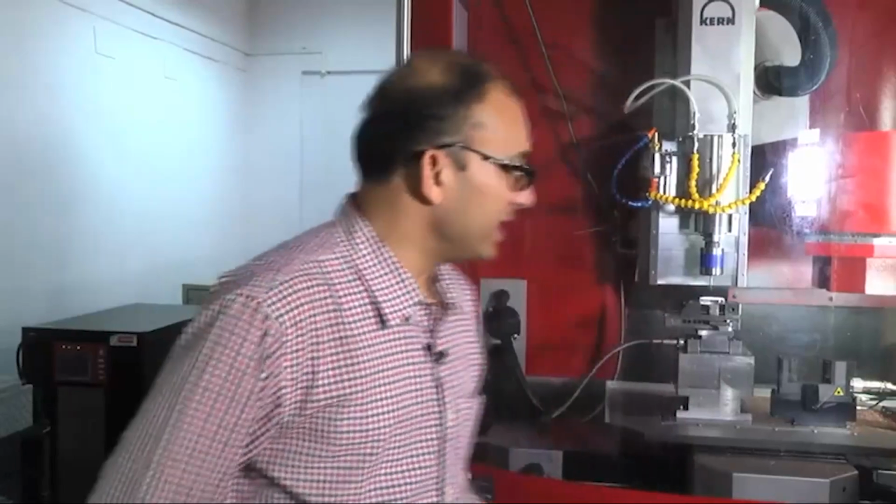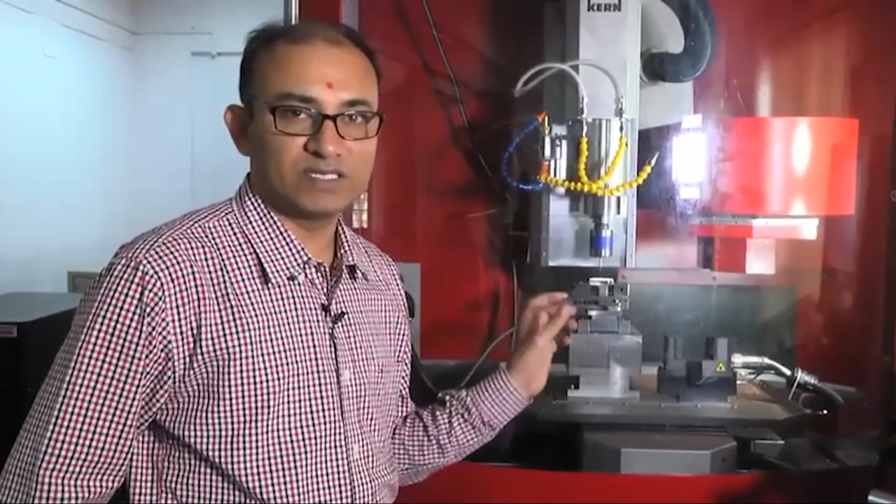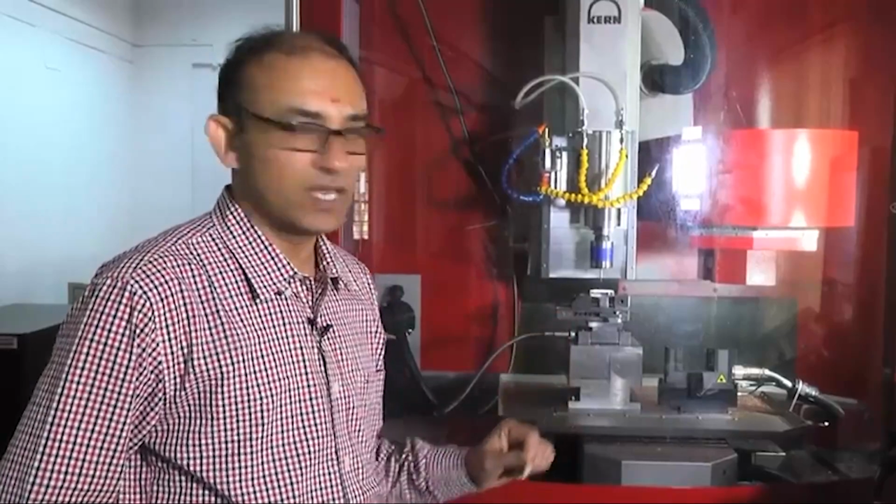What we are looking at here is a polymer PMMA workpiece fixed with the fixture, and there is a probe attached to the spindle. This probe is used for measurement of different dimensions of the workpiece, such as flatness. If it is a circular component, then we can measure the diameter as well as the radius. If it is other than circular, such as square or rectangular, then we can find the edges also.